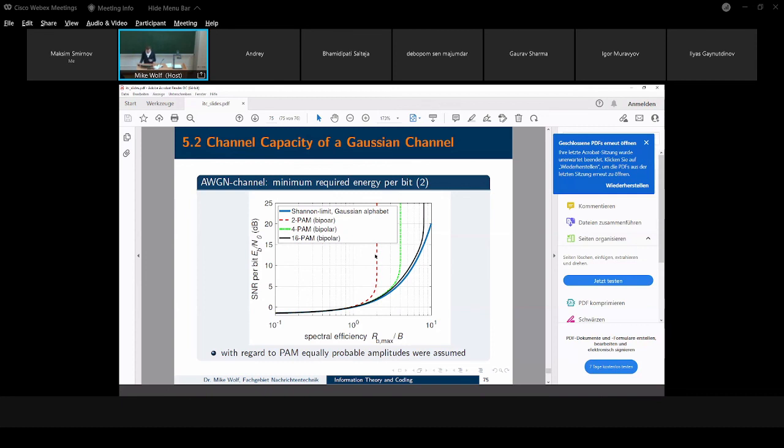And of course, if the noise is large, so if we don't have enough energy per bit, the bit rate is lower. Or on the other hand, if you make the bandwidth much larger than this bit rate, you can decrease the energy per bit. But you can never obtain a bit rate which is larger than 2B for binary transmission.